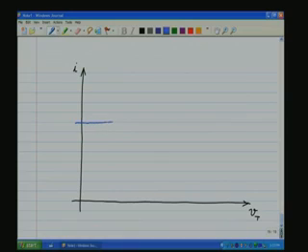So, which means a current source implies that I should have a horizontal line like that. A voltage source implies that I should have a vertical line, something like that. So, an ideal photovoltaic cell will fall within this square template that I have right now drawn here.